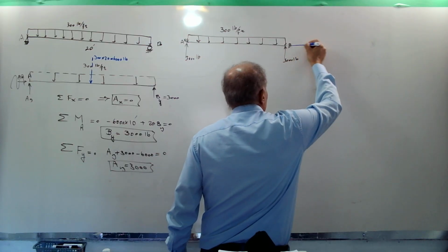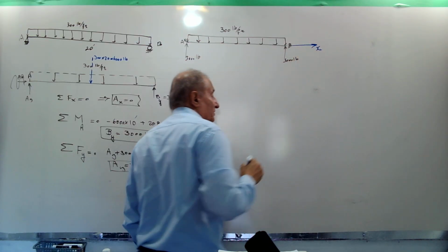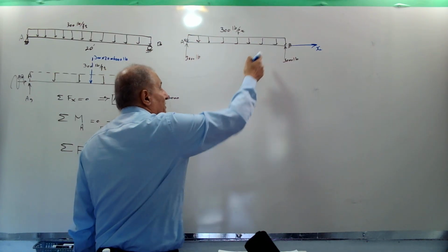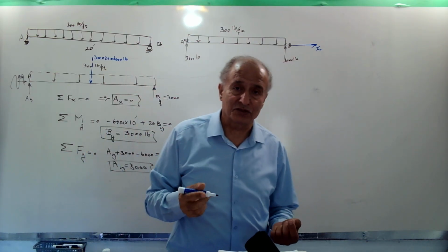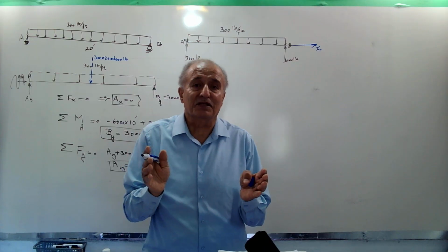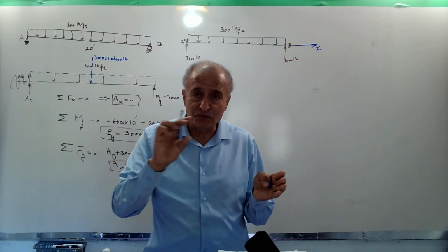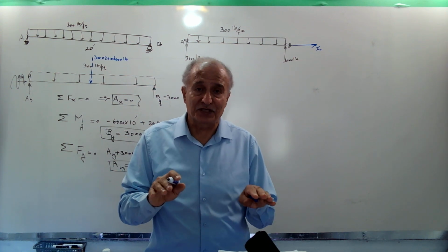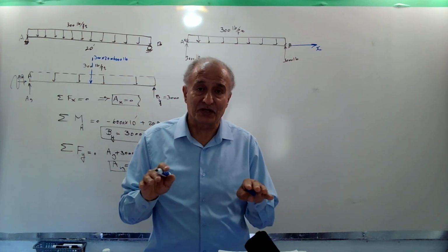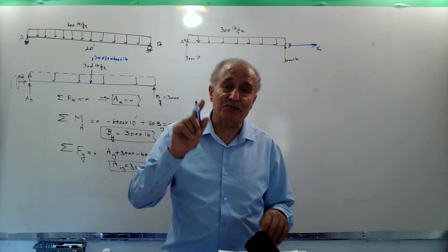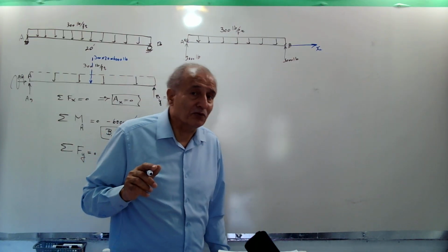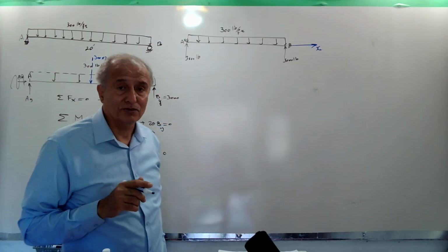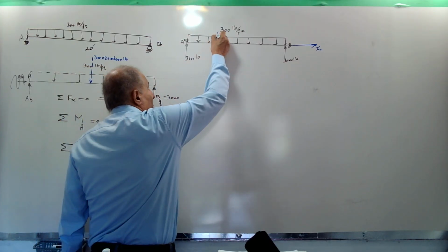and the direction of X to the right here. Because we have only one loading condition, one distributed load, I take the simplest form. A uniform distribution from A to B doesn't change. Because there is no change in the external load or loading conditions, we need only one imaginary cut through the beam. It doesn't matter where. You can cut here or here, you get the same result. Okay, I cut here.